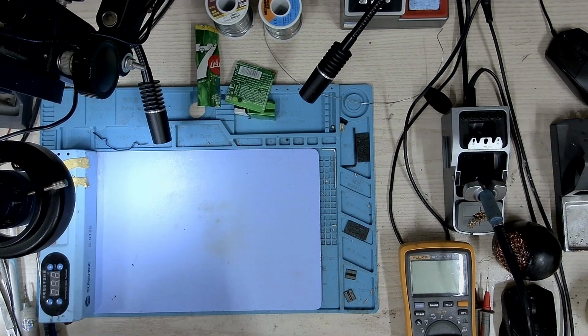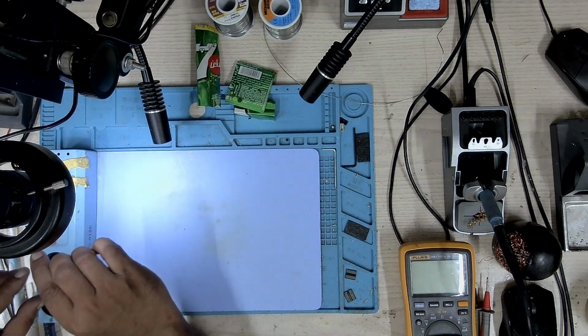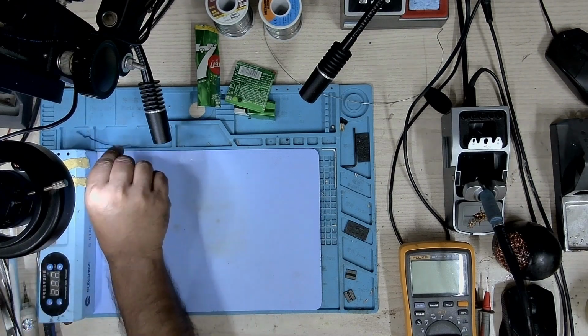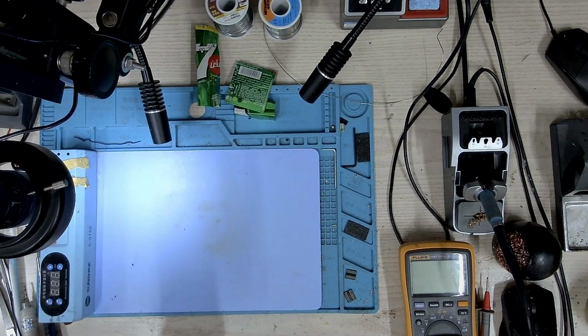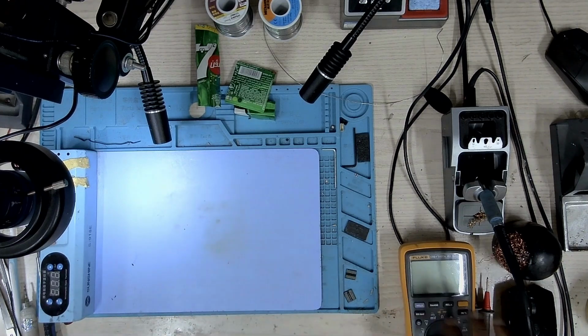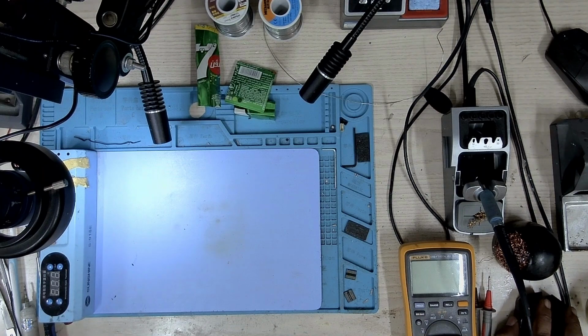We have another symptom where it will show code 43. Even if it shows code 43, I will show you what will show when we do the stress test. So what I'm going to do now is show you what it looks like when we try to test this card, for example, when we run MATS or when we run MODS, and that's the strange thing.